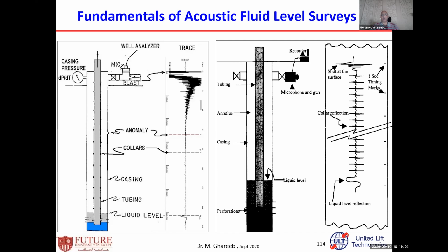There are different ways, but the main way is this: I know the tubing that is running in the well. I know from my workover tally sheet what tubing I have, and the average tubing length. Then I count, after I run this microphone and tool connected to the casing annulus, the number of tubing joints from surface up to the peak of the fluid level.